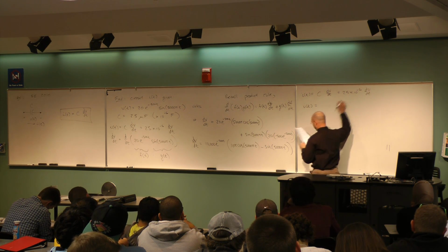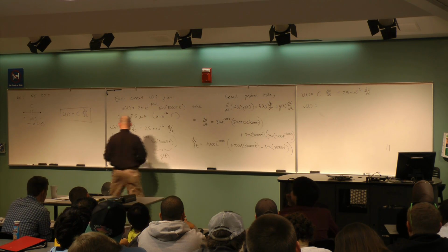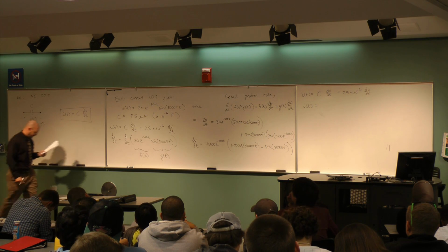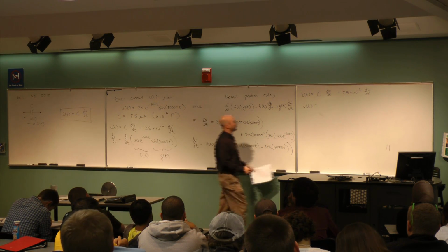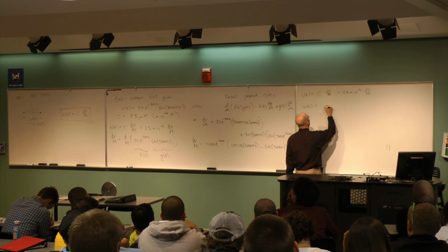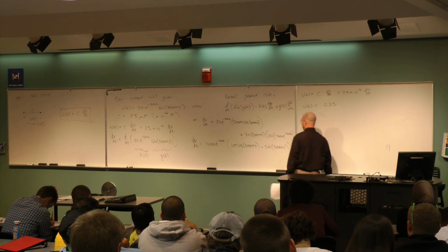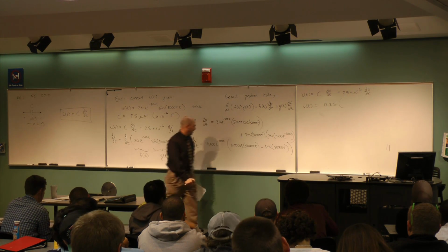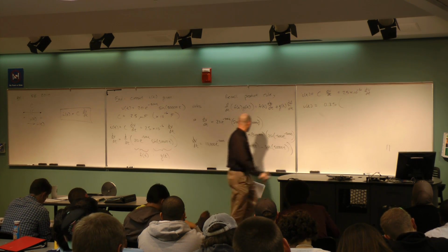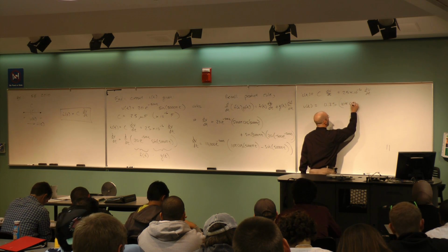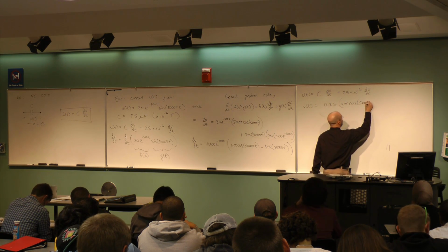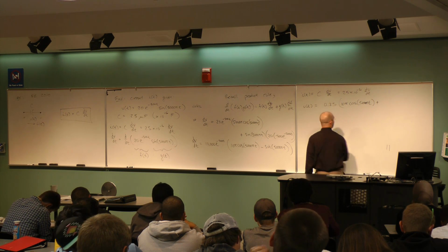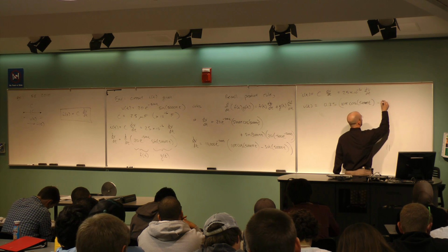Sorry, 2.5? Is that what I said it was? No, that's right. C dV/dt. It's 25. Yeah, Josh has a typo in the notes, off by a decimal point. So it's 25 e minus 2, 0.25, right, times what's left over here. Okay, and so again, I got the 10 pi cosine times 5,000 pi t. Then I have minus a sine 5,000 pi t.